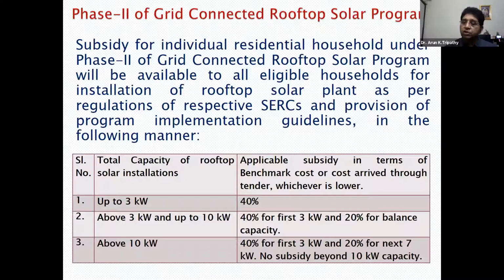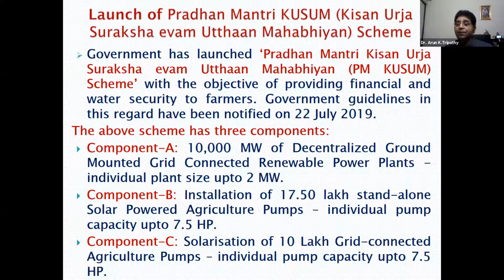And today, moreover, the cost of solar power installation at home has come down very much, ranging from 30,000 rupees per kilowatt to 40,000 rupees per kilowatt. Means if I want to install a 2 kilowatt plant, I can install it at 60,000 to 80,000 rupees, depending upon the different types of cells, area, and topography of the place. This gives a payback period of about 4 years. So in 4 years, we get our money back without any subsidy. If subsidy is there, then you get it in a very short period of time. Then in the next 20 years, we get free electricity.